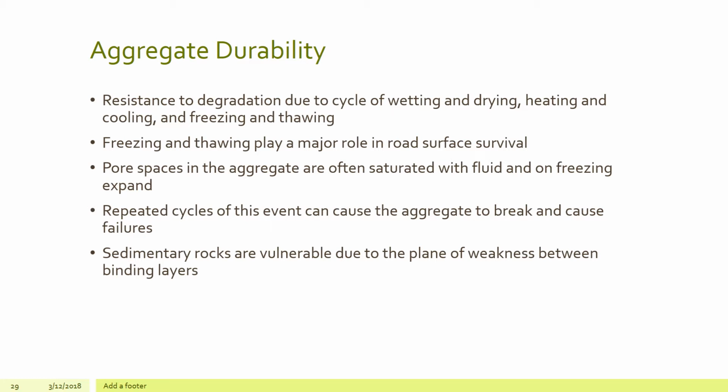Sedimentary rocks are vulnerable due to the plane of weakness between binding layers that we have. Soundness test, field performance, and absorption value are things that we could look at.